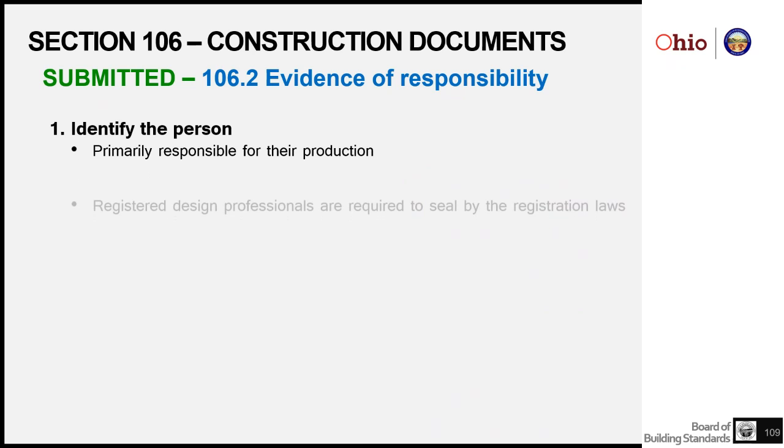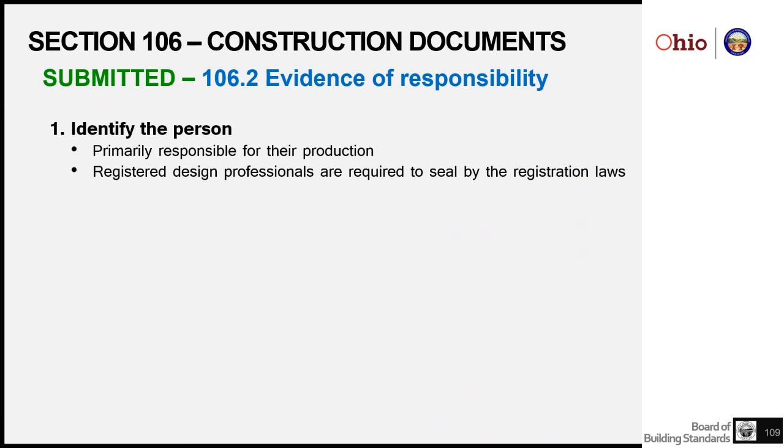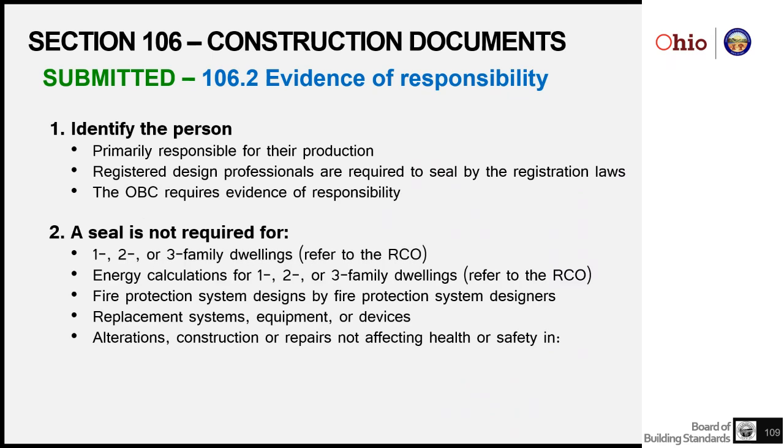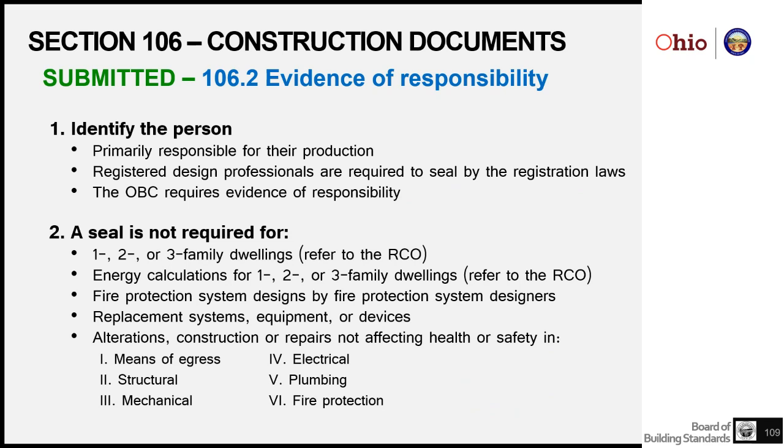Evidence of responsibility must be on the documents. Who is primarily responsible? The seal of a registered design professional is basically regulated by their registration laws, but we do require evidence of responsibility. A seal is not required for this list of items or types of buildings.